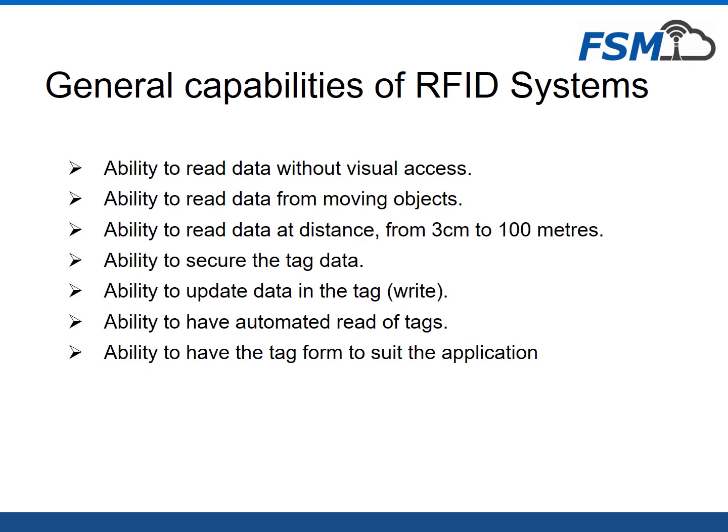Like in a manufacturing system, when a job work carrying RFID tags moves from one station to the other station, what work has been done on each station, what parameterization has been done, which operator was there, so to say, can also, depending on the need, be written back into the tag, which subsequently becomes a storehouse of a lot of information of all the processes it has gone through. Or even diagnostic data during manufacturing of an item can be written back and categorized and related to the item.